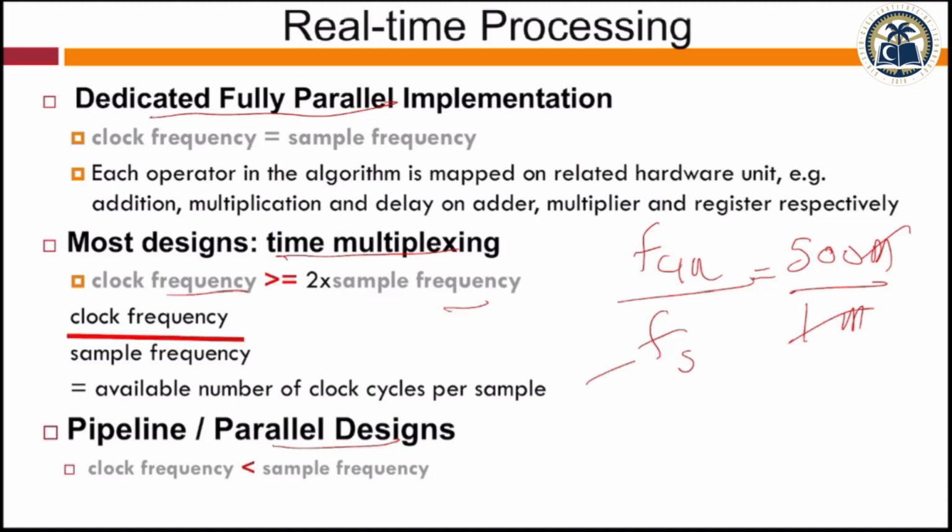So first of all, once you're doing a system level design, you have to find out the budget of every block, that how fast you want to run your block, knowing the target clock and knowing at what rate you are getting your data inside the processor. The processor has to process these many samples, worst case, in a second, and it has so many cycles in a second, so how many cycles do I have to process?